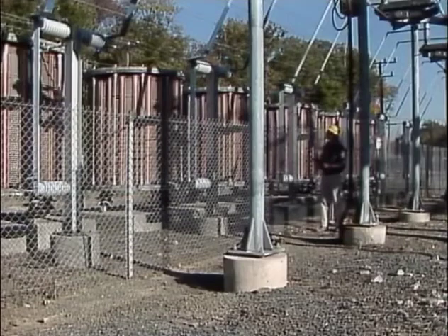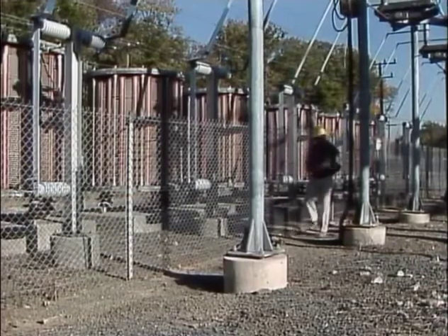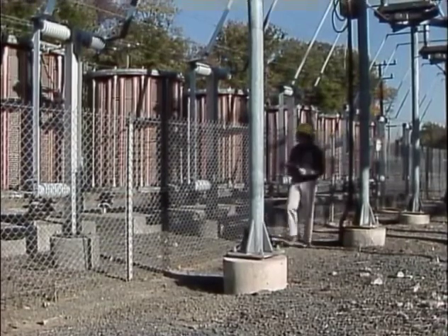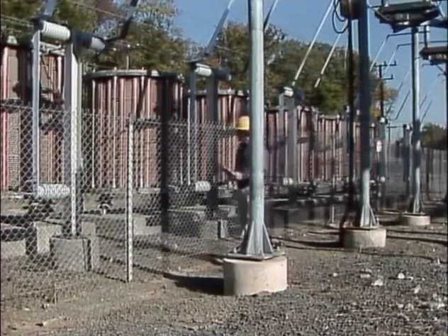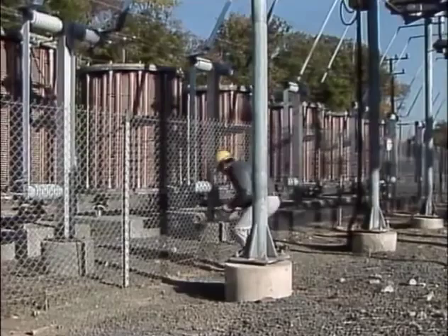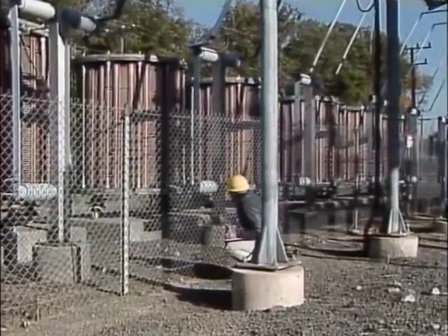Normally, a visual inspection is all that is required. Care should be taken to stay a safe distance from an air core shunt reactor while it is energized. The main visual checks include the support insulators and the winding shims.